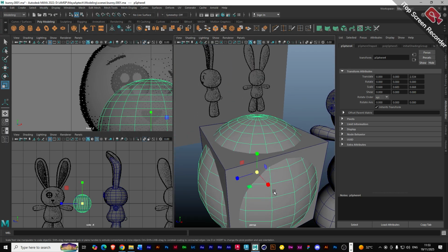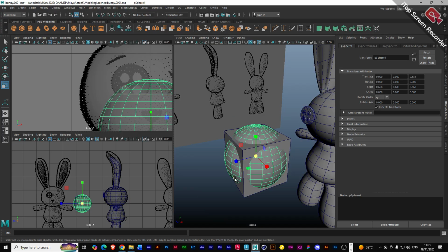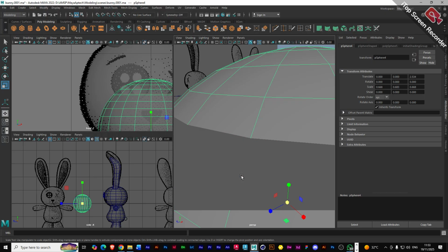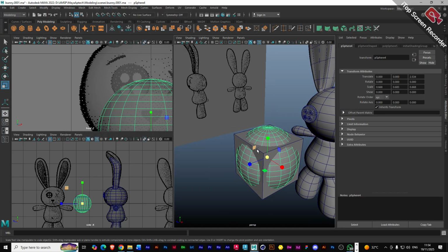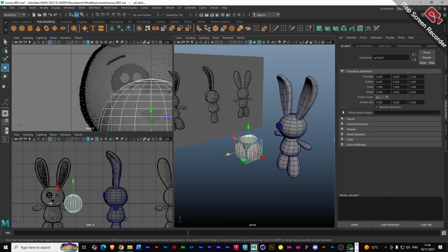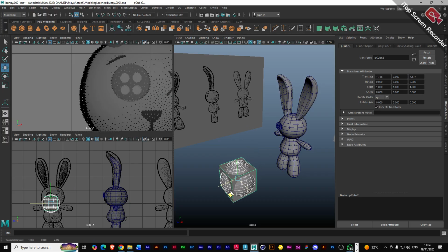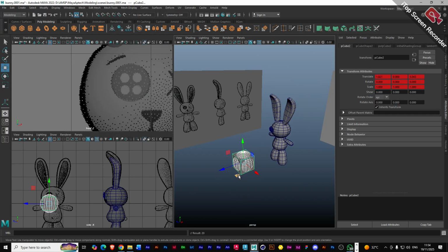Okay, so under Boolean is a mesh property that has to work on the objects as a whole. For it to work, we have to have both objects selected, and the order in which you select them is important.